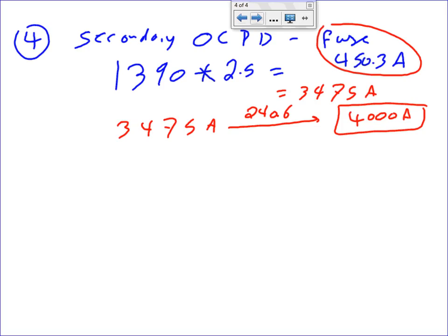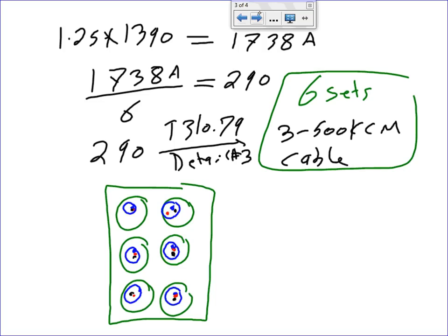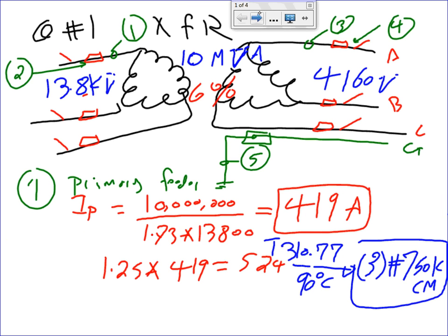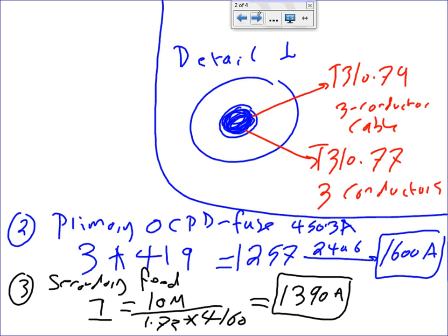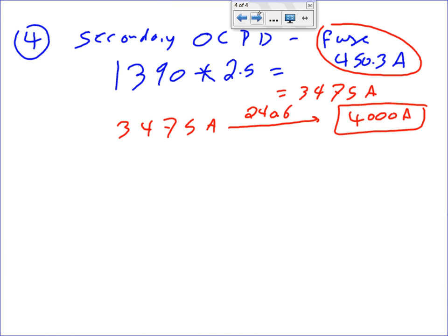You know, you have to have the fuse. By the way, fuses, guys, have to have a disconnect. That's why I showed fuse and a disconnect right with it, because they want you to be able to isolate the system. A fuse cannot be used as an isolation means by itself. First you disconnect it, and then you go grab it and change it. Unlike a circuit breaker, where you can isolate the system with the circuit breaker. Number 4. The last thing is number 5, guys.